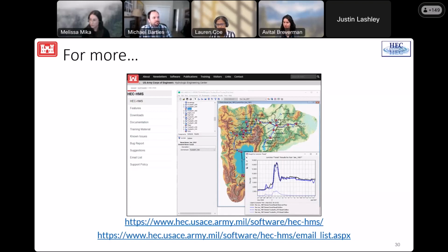All right, next question from Michelle. For temperature disaggregation, is it possible to change the hours of daily low and high temperatures? Throughout the simulation time period, currently you set the time of high temperature, and the daily low will change throughout the year. So over the summer, the sun rises earlier in the day, so you get a time of low temperature earlier in the day than in the winter, at least in the northern hemisphere. That will work the other way if you wanted to use this in the southern hemisphere. So the low changes throughout the day, but the high temperature stays the same. We could implement parameter value patterns for that one as well. If you're interested, hit us up and we can talk about that.